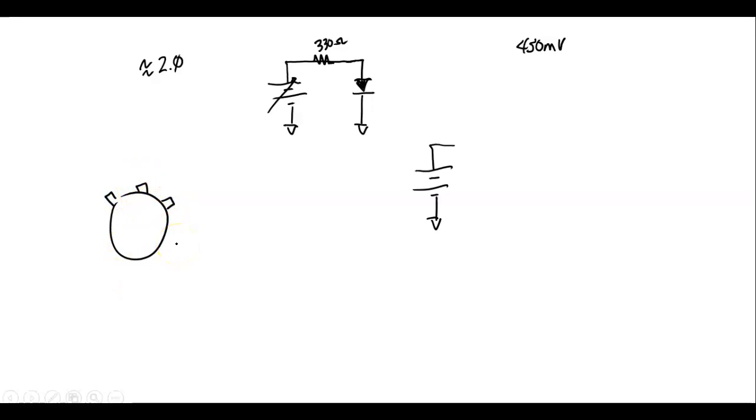And then we got a knob on it. And it's real easy to see. Normally, this will be one side. This right here, this is what's important. This is what we refer to as the wiper. That's where we're going to vary the voltage. So what we want to vary the voltage across, we come over here and we put it between the two outsides.